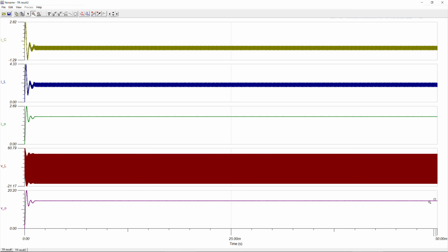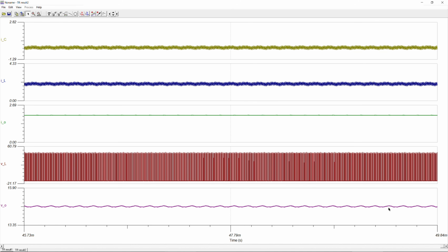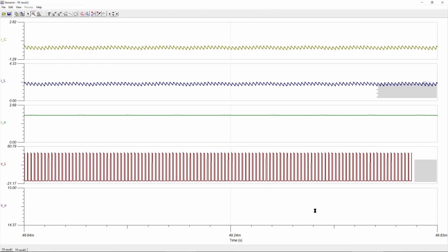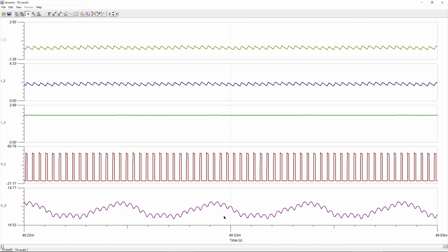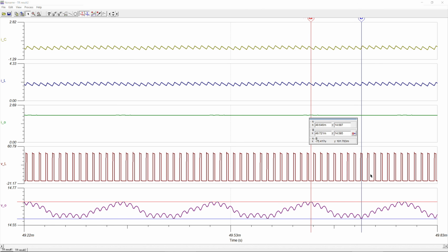And if I now zoom in a little bit more, here is the output, and again zoom in, because I want to now see the peak at the output. And again zoom in. Now take the cursor again and check the output peak value, and indeed verify that increasing the capacitor will decrease the output ripple voltage. Now I will take this. You see here 102 millivolts as our peak output voltage, which is much smaller than the 150 millivolts we are allowed to have for this design.